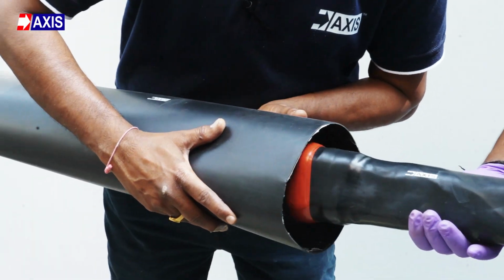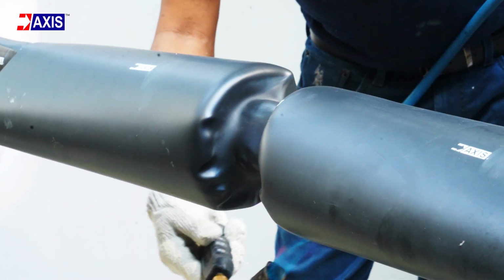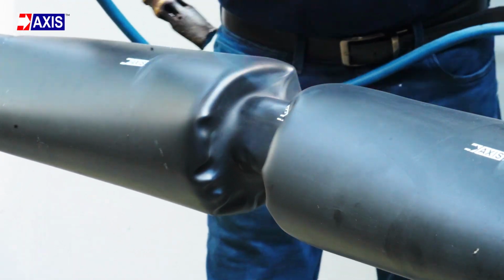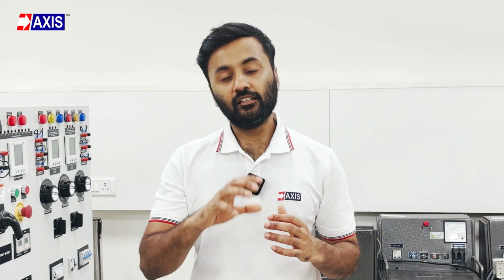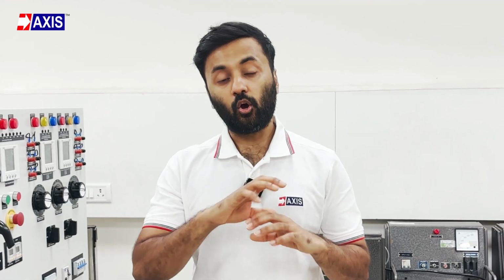Imagine you're working with a power cable that has a thick lug at one end and a thinner cable section behind it. You need one tube that can slide over the connector and still shrink down tightly around the cable. Standard tubing won't cover both properly. You need something that can handle the size difference without leaving gaps. This is where shrink ratios come in. These ratios tell you how much the tube reduces in diameter when heat is applied, allowing a single tube to adapt to different sizes along the same length.